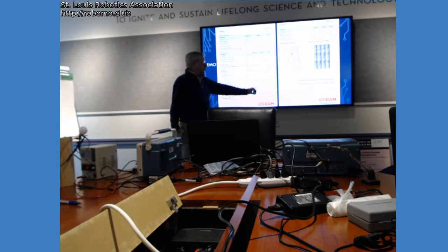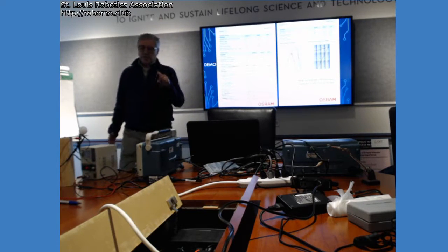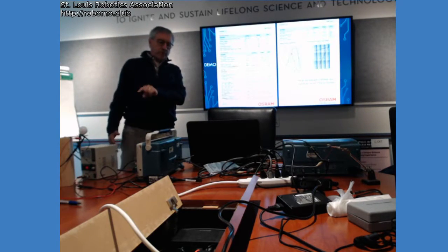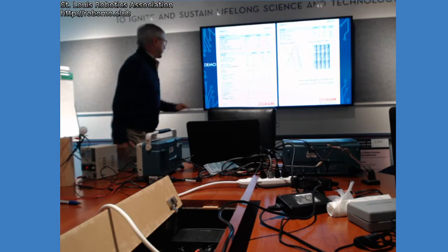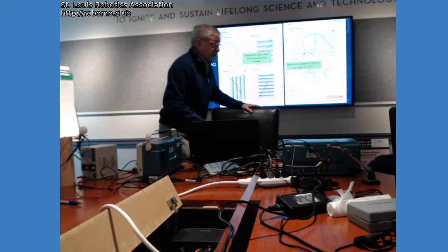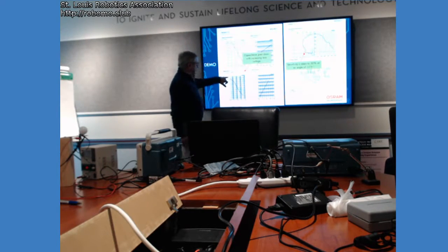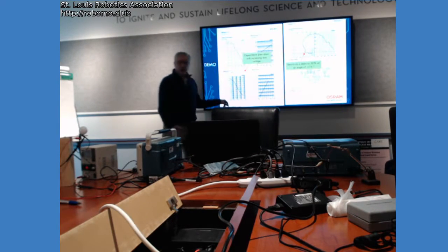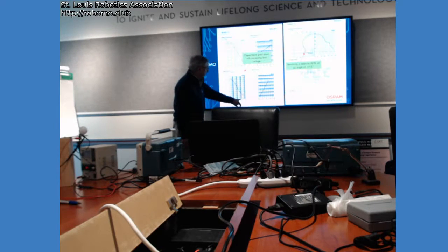Capacitance is 11 picofarads, and in fact it will be even less because we've got reverse bias. Here's the curve for the capacitance. You can't read it, I'm sorry, but if you get up to about 5 volts, instead of 11 picofarads you're down to about 4.